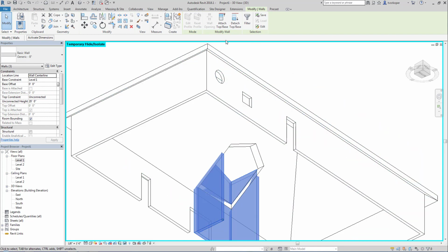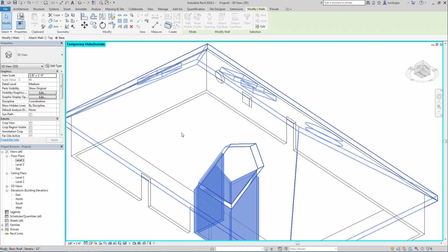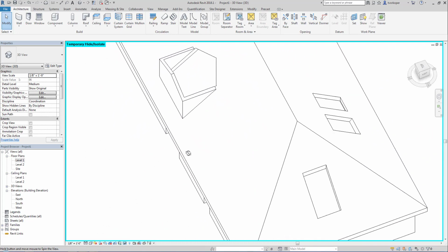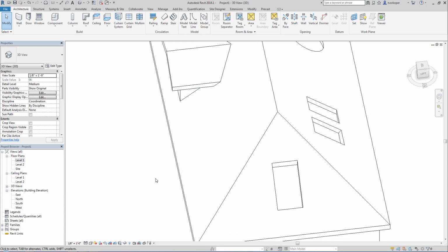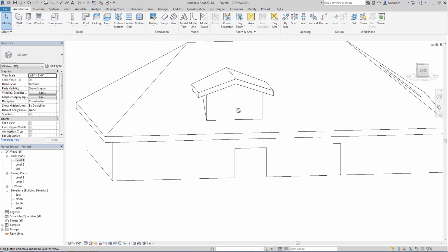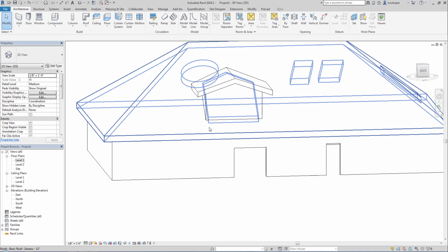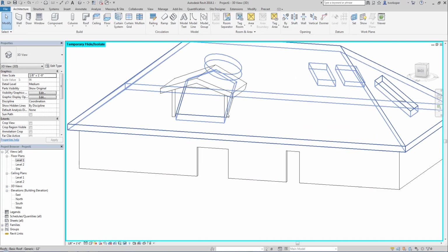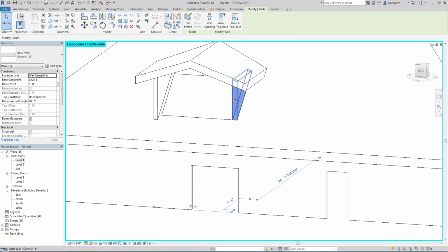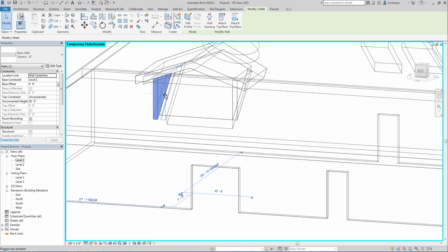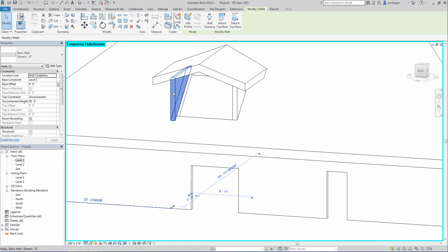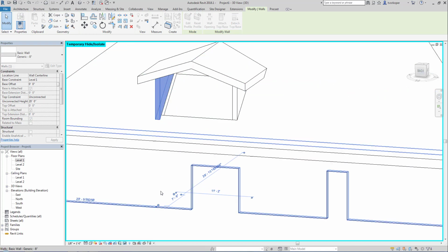We might want to take these 3 walls and attach the base of those walls to the roof, and now you can see that the dormer is modeled the way it would be built. HR resets my roof, and now I have a dormer with an opening below. I'm going to go ahead and hide the front wall so we can take a look at what happens if we actually moved one of these walls. If I took this far wall and I wanted it a little bit more narrow, you can see that the opening followed, as well as the roof. That's the strength of the dormer opening.